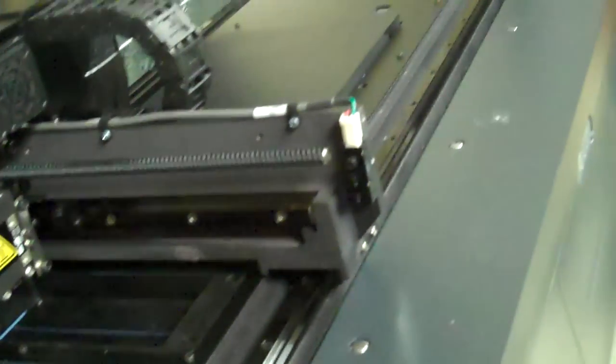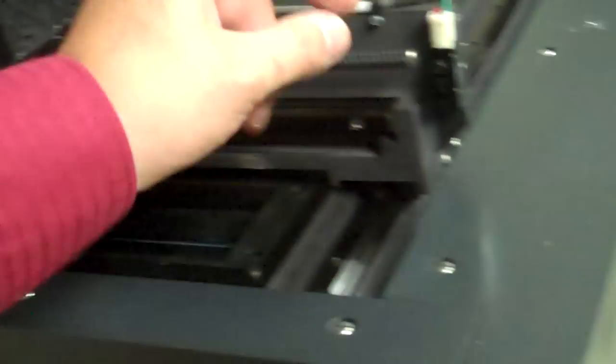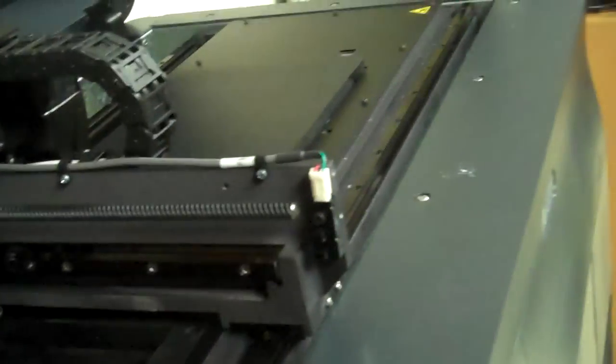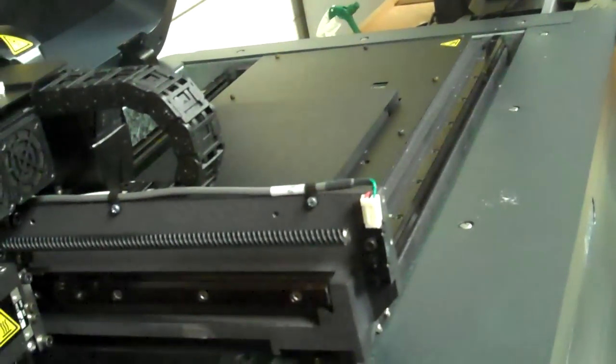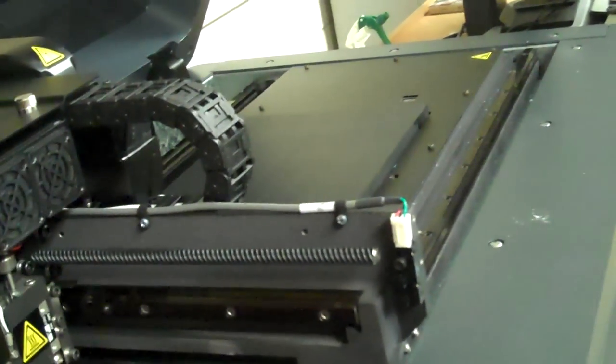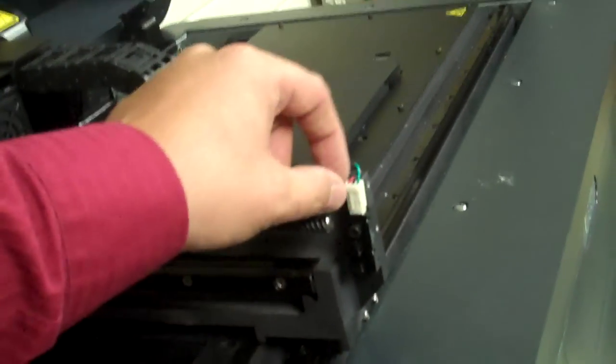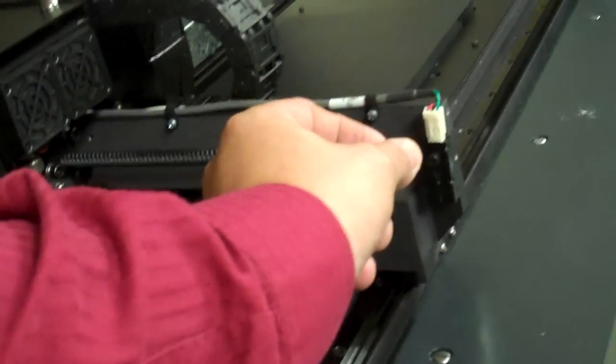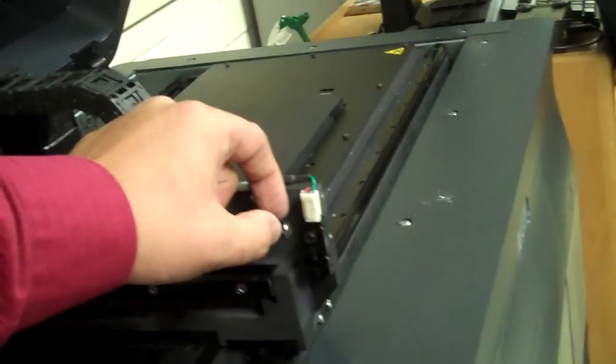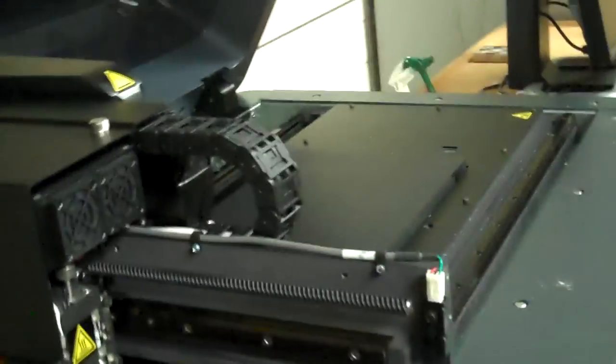And so why do they do that? Make it quicker. So that it can move faster. Yeah, so you move faster. Why not just make the threads further apart? It'd make them deeper, right? Could you make a thread this wide and that deep? It would make it weaker. It wouldn't fit on this piece here, right? So that's why we do multiple lead. So we can keep the thread depth down, but increase how fast things will move along it.